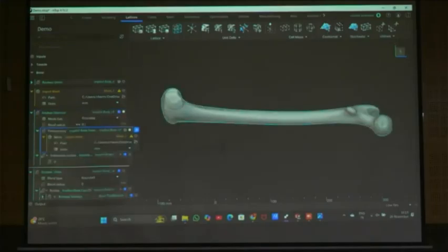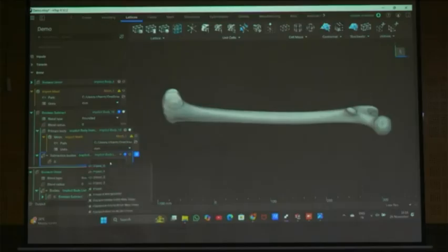The remaining blend radius I am not exploring. You can get it in the help also. I will keep this as the same. So what I will do is subtract with the plane. So the subtraction body is the plane. This body is there, right? One body is there, and I am applying a subtraction here with respect to this plane. So this body can separate from the primary body, okay? So I will take plane from normal.